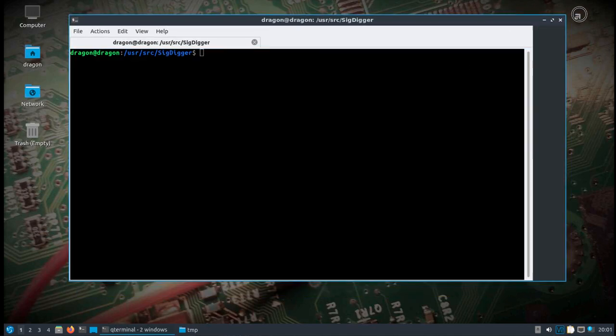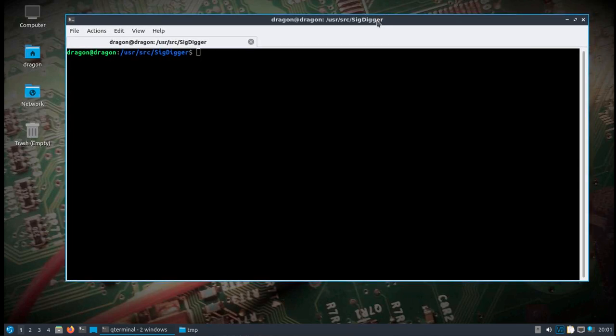What we're going to do is take the RTL-SDR and make a profile that is going to be shared over the network to SigDigger on another computer. The benefit of this is it's very efficient with bandwidth usage, and it can work outside the local network. All the digital signal processing is happening on the Intel NUC itself, and over on the laptop it's basically just going to be the shell that's presenting us the information and allowing us to control the Intel NUC and SigDigger.